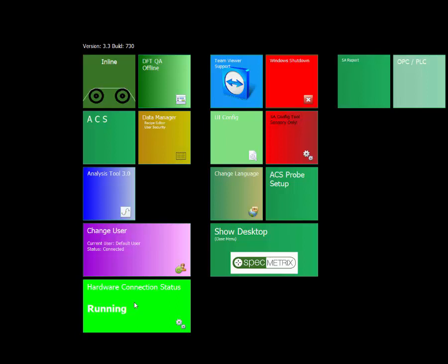A secondary final note is that you can no longer just copy a configuration from one system to another and skip the process of setting up traversing. The traversing really is very specific now from system to system, so you do want to make sure you're not copying secondary systems over and trying to circumvent a shortcut process, because the dimensions of the beams, where they're mounted, and how they're associated with respect to the rollers and other hardware may be very different.